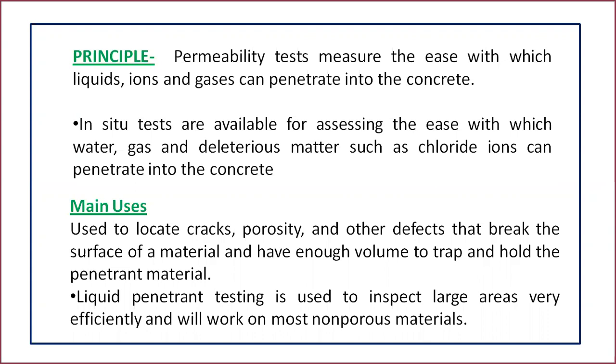And all of these binders, at different levels, protect the entire construction of this concrete bed. Even so, it is exposed to liquids or gases which have the capability of penetrating into it, with respect to water and gas, and even deleterious matter such as chloride ions that penetrate into the concrete. So at what level is it getting penetrated? How far the different layers protecting that particular concrete bed are being penetrated can be clearly identified in this testing process.